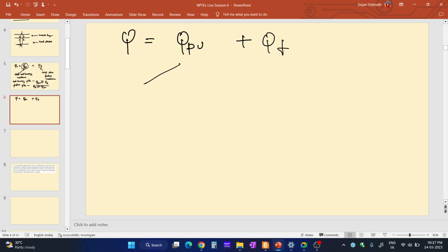So this QPU term we can write again. Since QPU, that is the total end bearing resistance, involves the tip of the pile, that means the load is transferring to the bedrock or maybe hard stratum through the tip of the pile.